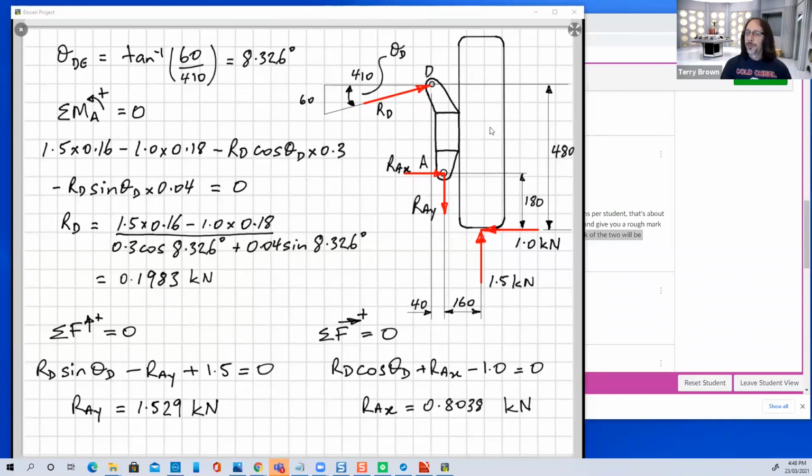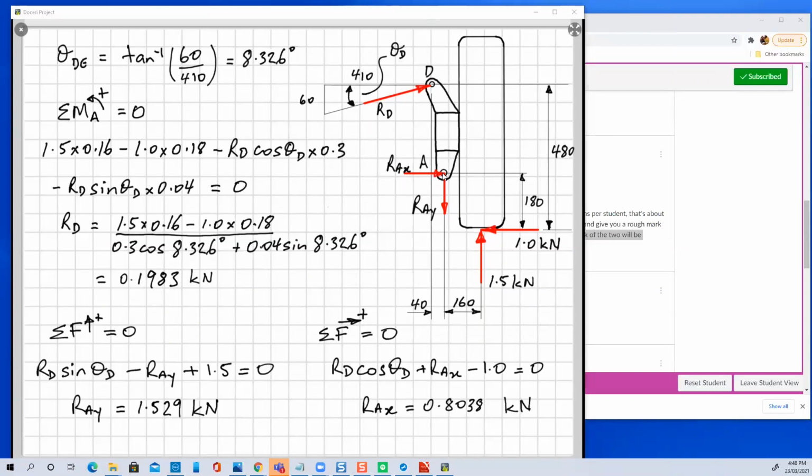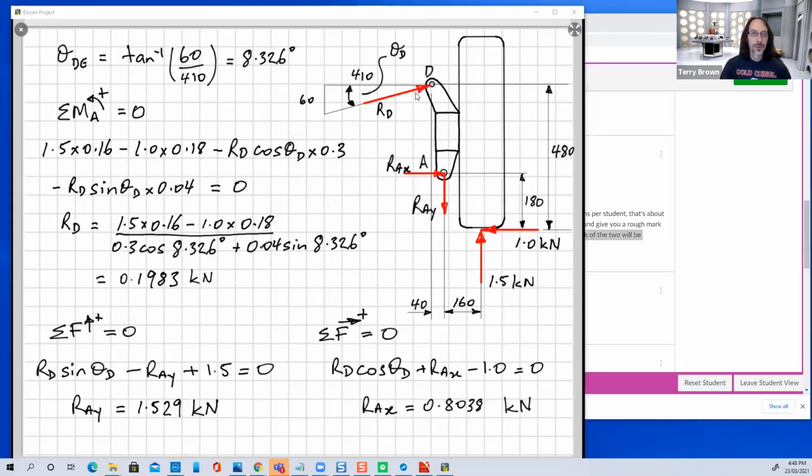When you have a rigid body equilibrium problem, nearly always, 90% or more of the time, the best thing to do is to take moments about the point where your 2 unknown reactions are. Mostly you'll have either a pin connection and a roller, or a smooth contact, or connection to a 2-force member.